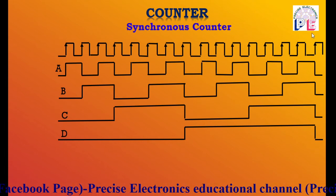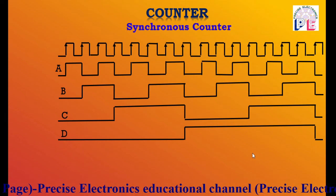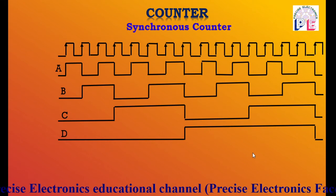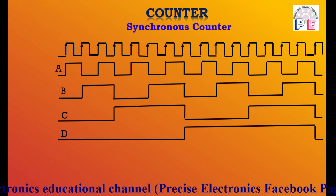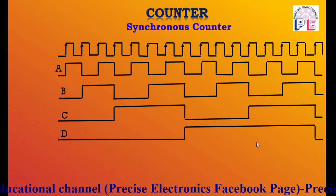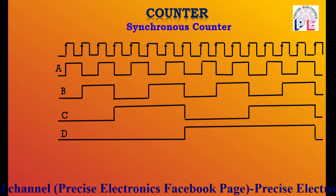So the fourth flip-flop is in toggle mode and the transition of state occurs. So at the 16th clock pulse, the output of the first flip-flop changes from 1 to 0, goes into reset mode. B also changes from 1 to 0, C also changes from 1 to 0, and the D flip-flop, that is the fourth flip-flop, also changes state from 1 to 0.